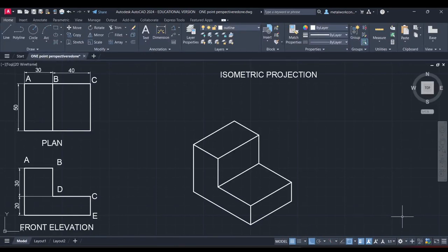When you're finished drawing an isometric drawing, this is what it would look like. You wouldn't put on the angles, say 30 degrees. Likewise, with the oblique projection, you just draw it at 30 when you're drawing it with the CAD or the T-square, the angle would be 30, but you wouldn't put it on. As I showed, it's just for your understanding that I put it there to show that the receding lines are drawn at 30 degrees to the horizontal.